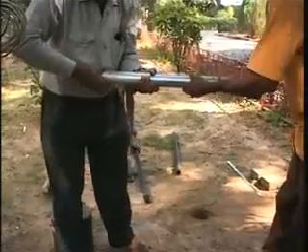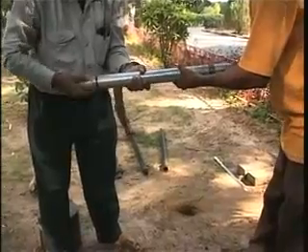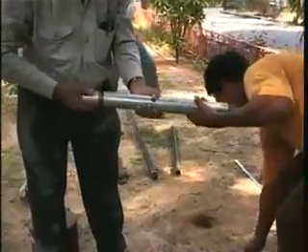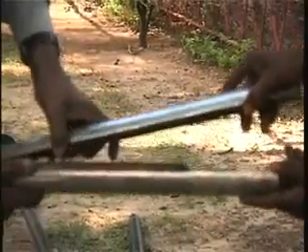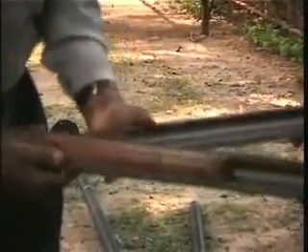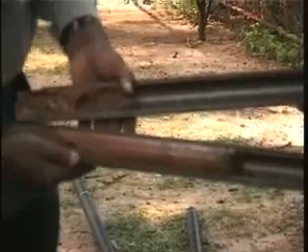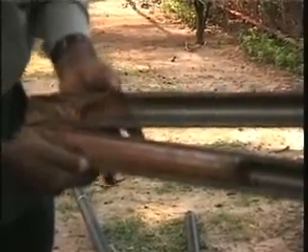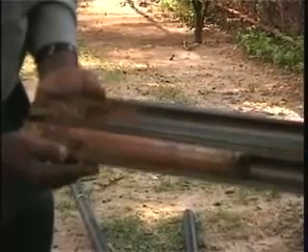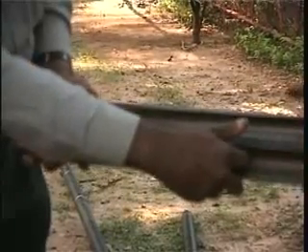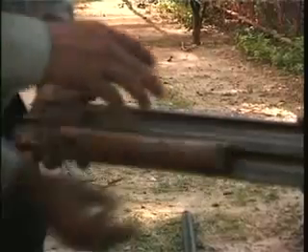Okay, now we have got the soil sample out from the ground, and we are going to disassemble the sampler and see how the sampler looks, how the soil sample looks. So this is the soil sample that we got from down there, and this particular sample is visually identified in the field, and it is also saved. Some of these samples are also going to be saved for moisture content determination.